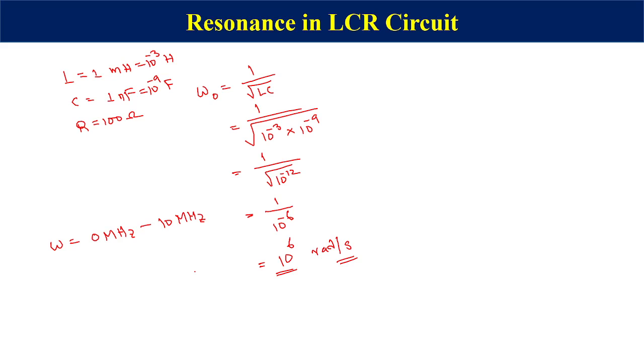The exact meaning is that inside the radio we have a variable capacitor and, let's say, a fixed inductor. Once you tune it, that means you change the value of the capacitance and you change the value of omega naught, that means the resonant frequency. Now if that particular frequency matches up with the frequency at which one particular channel is transmitting, in that case we get that channel.